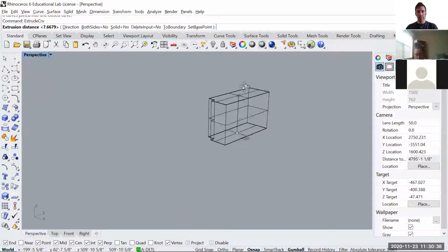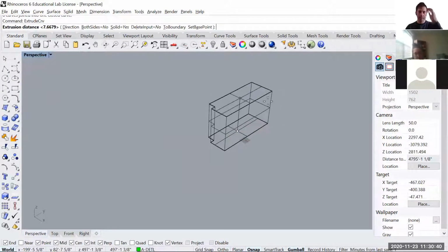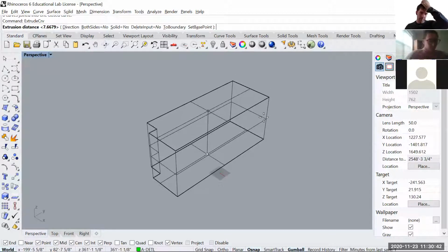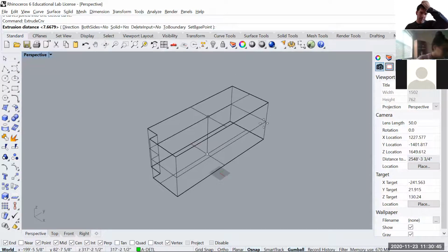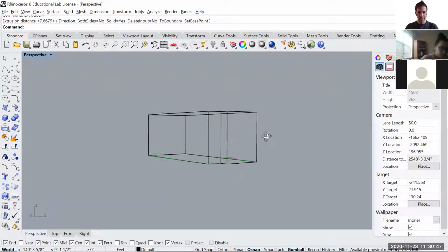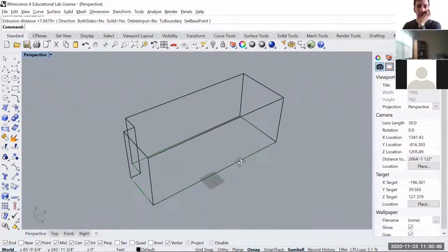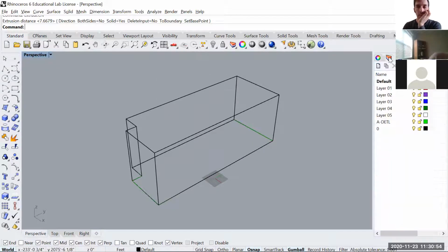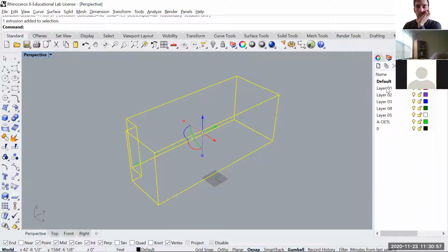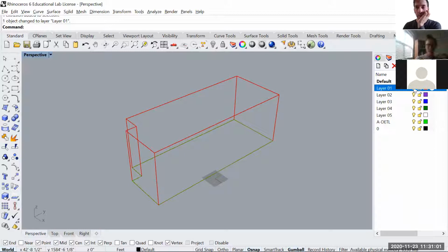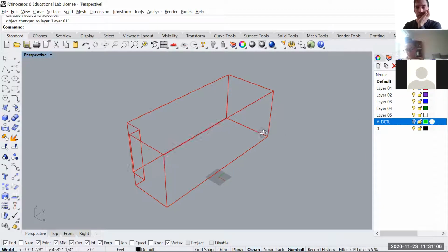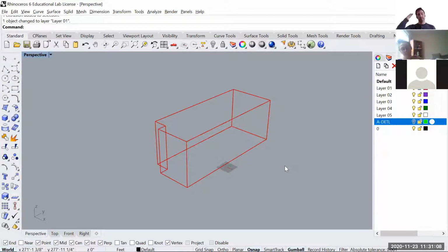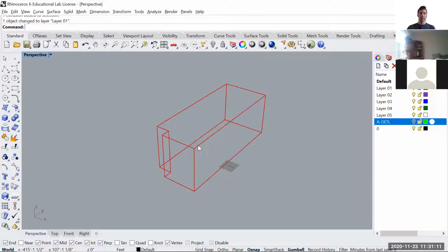If you extrude this as a volume, you can already set the height. I'm not sure of the height. I don't even know if the scale is 29 feet, and the lines are not accurate as well. So let's imagine this is a space. Now you can obviously work with layers. You can right-click, change your layer, lock it, and turn it off and on whenever you want. The detail you can turn off now because we don't need it. So we have this volume, we have the heights, etc.